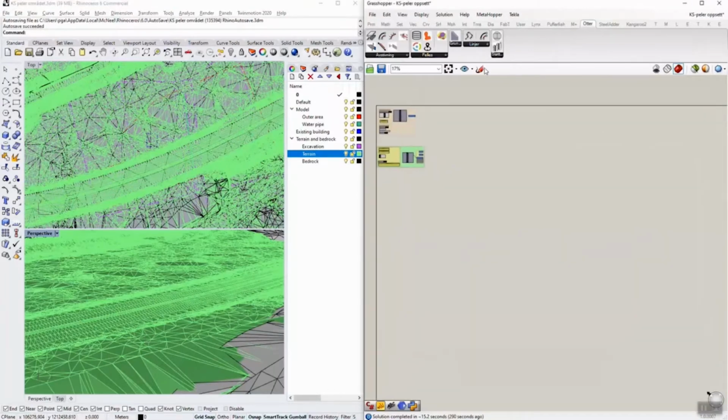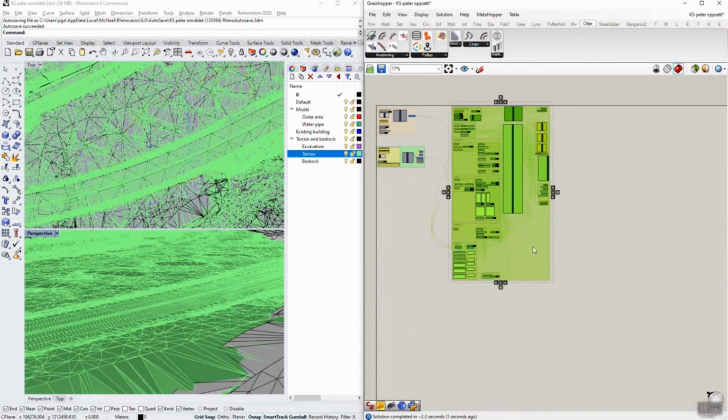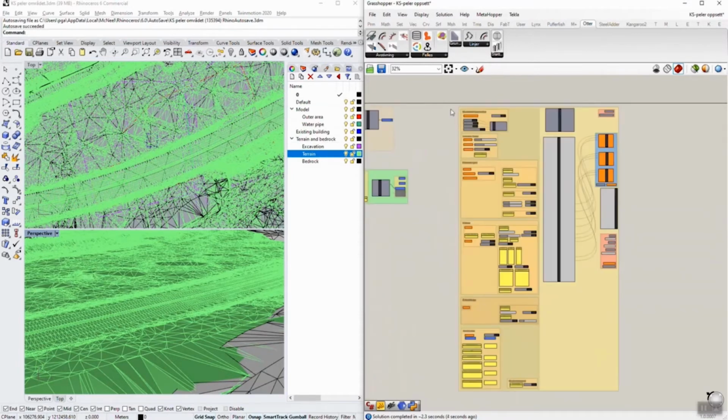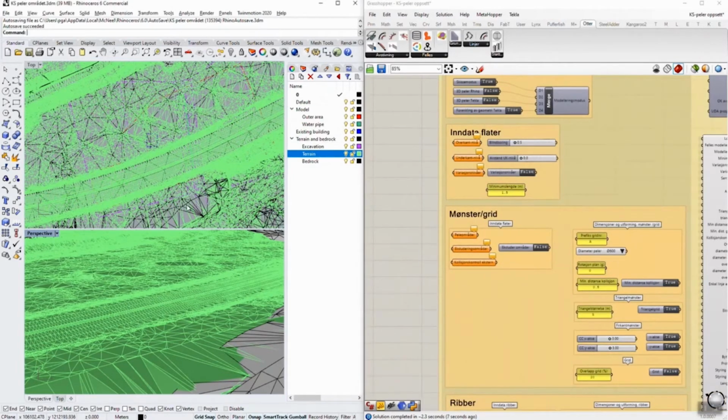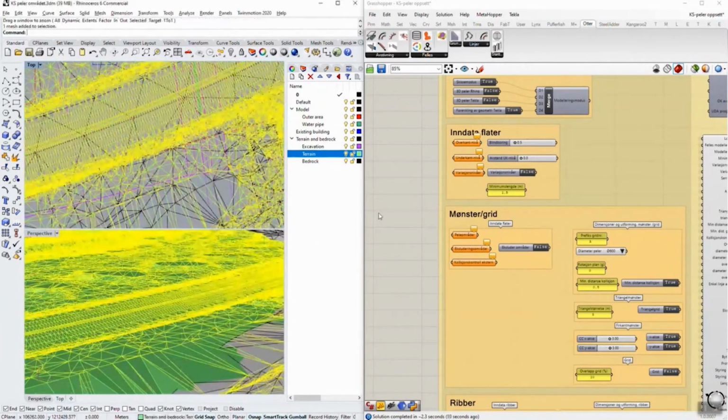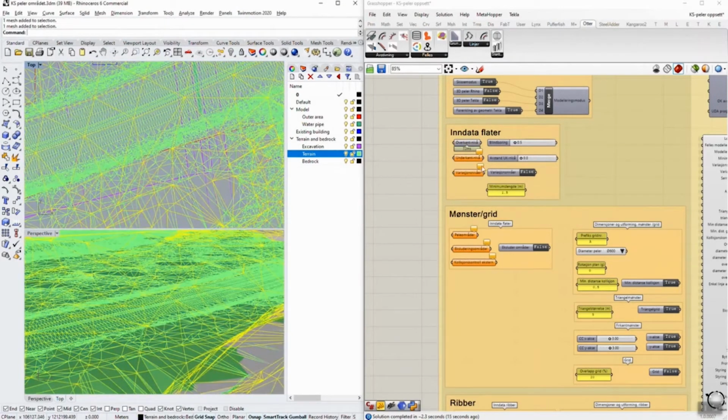And the reason for these different object types is that they are a good example to let you see how we, simply and dynamically, can have different types of deep soil mixing patterns, like Mats explained, merged together, as well as differentiating between the strength in one single column. So switching to Grasshopper, I've already prepared my script. I've imported the transformation part, and I've already taken in the attribute part, and so we'll just start with applying our deep soil mixing component. Setting our input data in Grasshopper, as we used to.